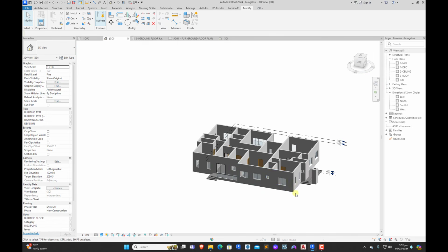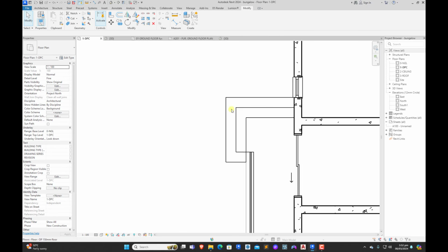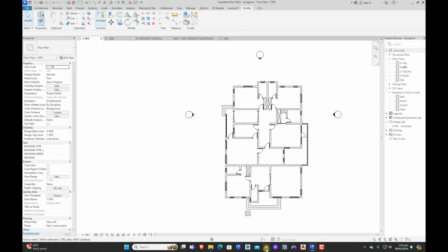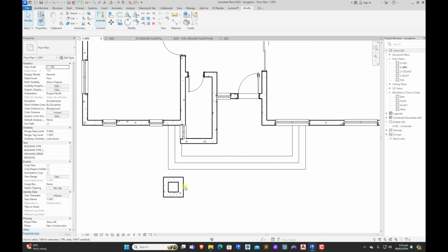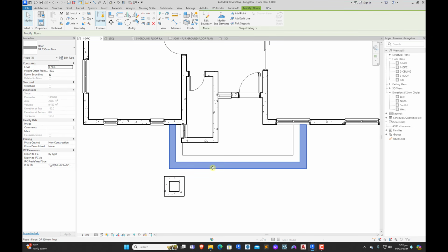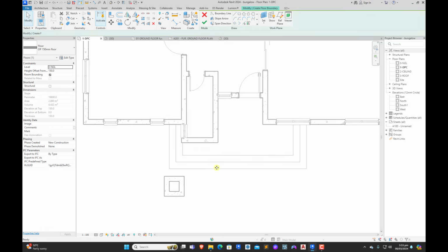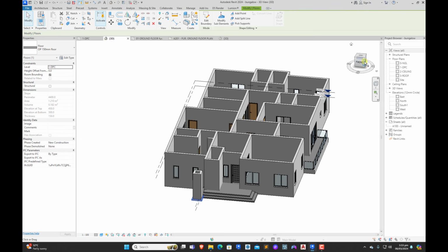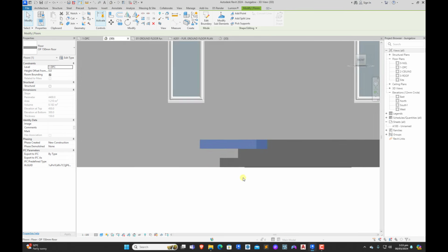Okay, so now for the column, what we're going to do in the column is we want to give it a very nice design. So let's say this is the first layer. Then we're going to be using a floor. You click on the floor, CS to create similar. You take an offset, use your rectangle tool. You give an offset of, let's say, 100 millimeters. This way. Okay. You come to your 3D so you see what you are actually doing.